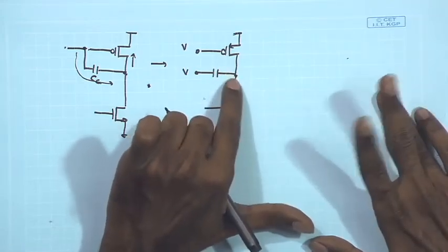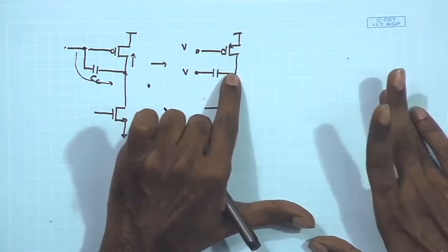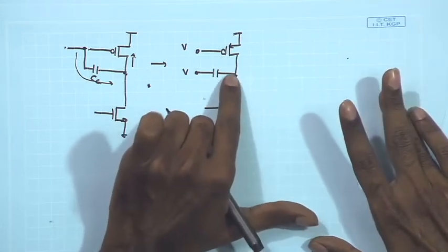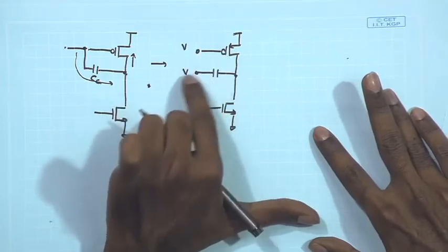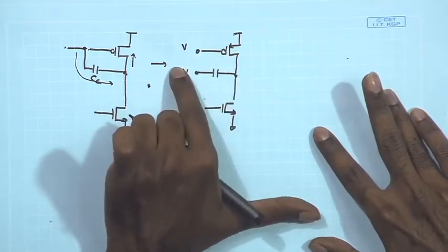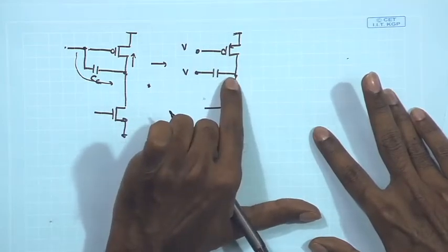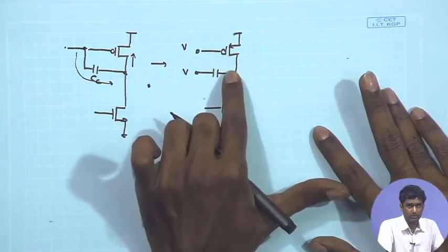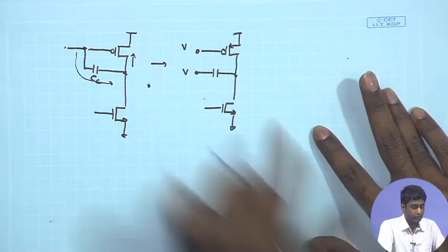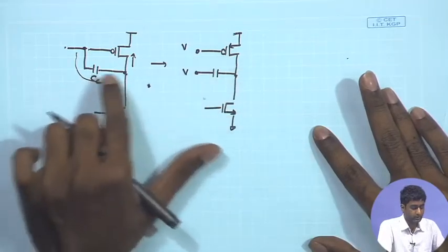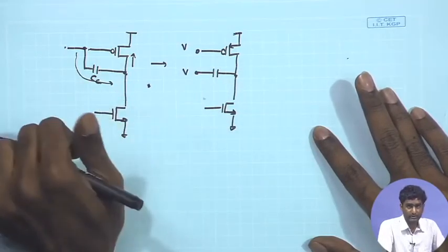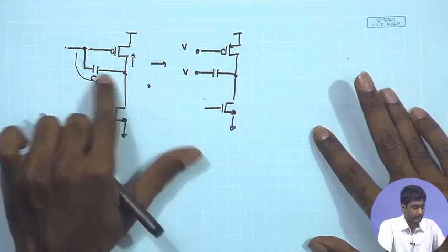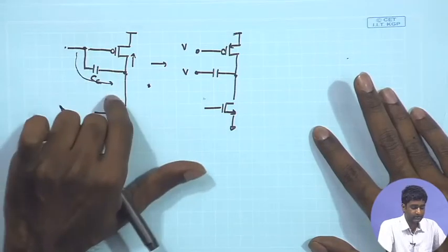At a particular frequency, if they cancel out each other, then you have a zero, because the overall small signal coming from these two paths, the inverting one and the non-inverting one, will be 0. That is going to give us the frequencies of the zero in this circuit. So far we have ignored the zeros, because we are taking approximate analysis. We are assuming the Miller effect and breaking down the capacitance at different nodes.